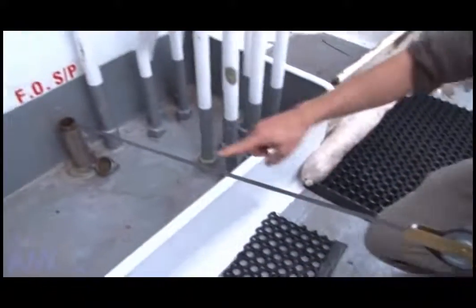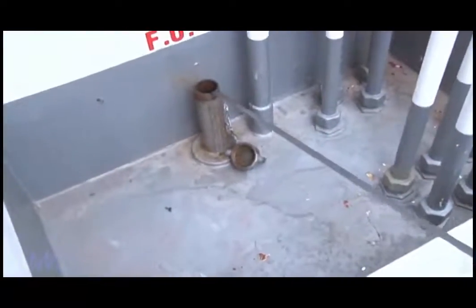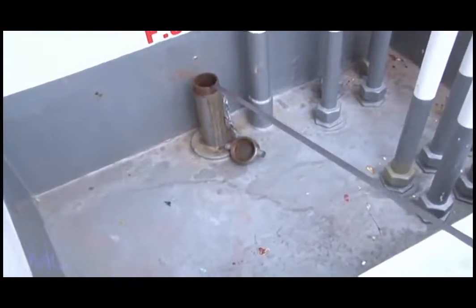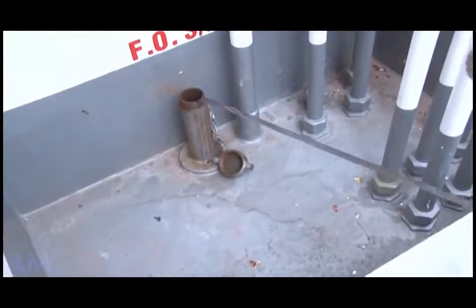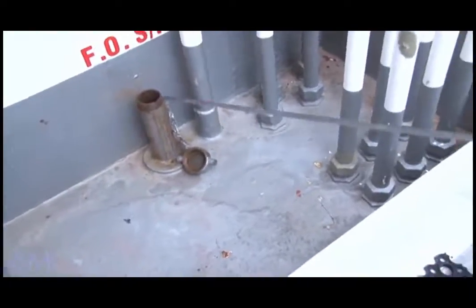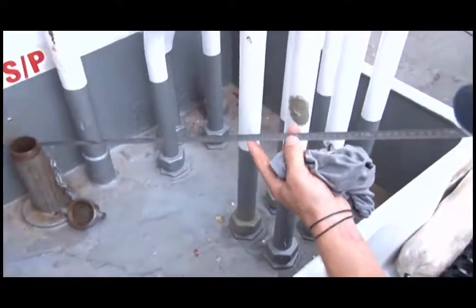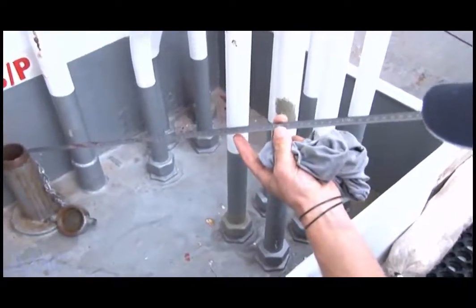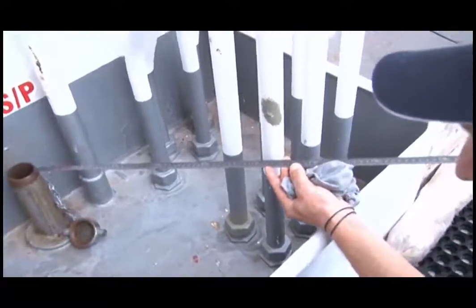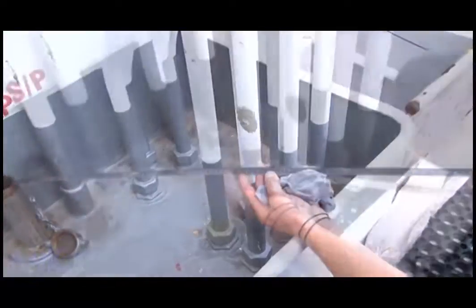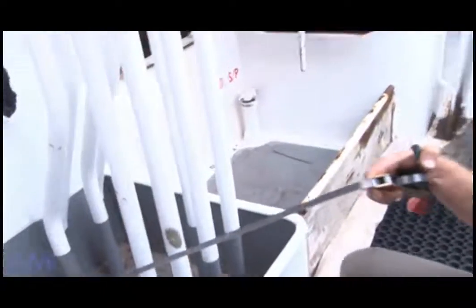So I get into a place where I can see reflection from the light, and I'll just keep winding until I see the level. With a bit of practice you get quite good at reading what the level is. So it's getting really shiny around this vicinity, and I can see just in the light where my level is right here. So I've got 1.20 metres. So that's the level right now. Once I've established that, I'll note that and we can work out what the volume is.